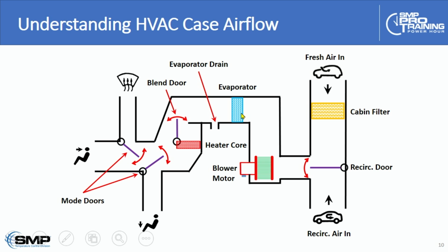So we chill the air first, and then pass it through the heater core and up to the windshield to defog or de-ice it. So for defog or defrost to work, the air conditioning has to work, and that can be a common complaint in the wintertime. The air coming out of the vent feels pretty hot, but it's still not as effective as it used to be at defogging or de-icing the windshield, and that may be because the compressor, the AC, is not running as it should in cold weather in defrost mode.